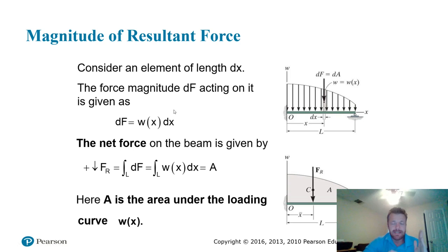So how would I actually determine the entire force acting upon that beam? Well, all that I would need to do is repeat that process across the entire beam. I would need to sum all of these little dFs. And that's exactly what we're doing here by calculus. I'm integrating over the entire length of the beam, which allows me to sum these infinitesimal forces. Substituting in, each little infinitesimal force is just the value of the density function times dx.